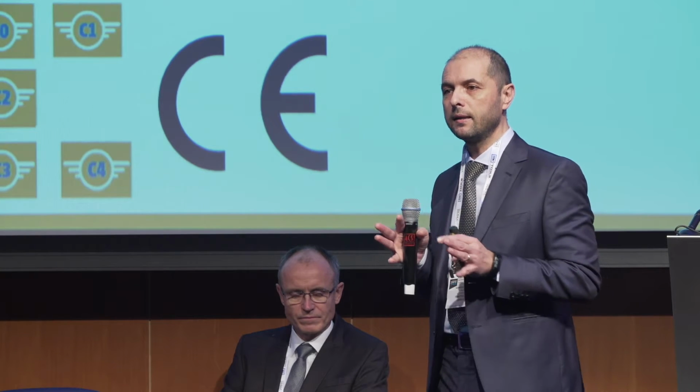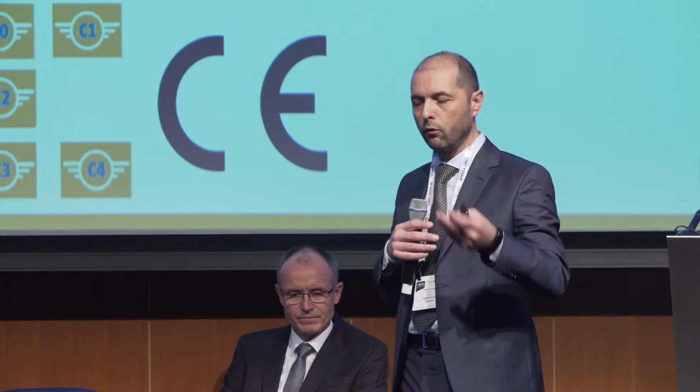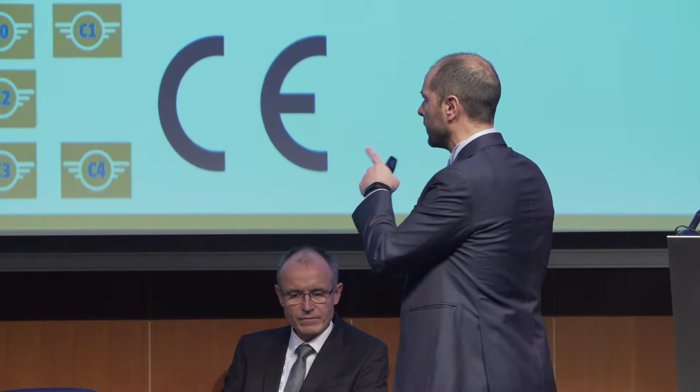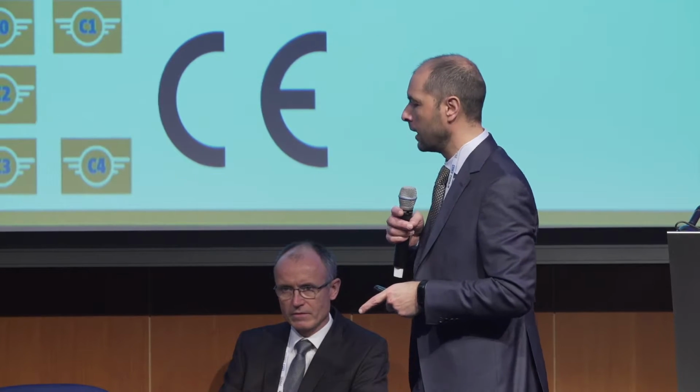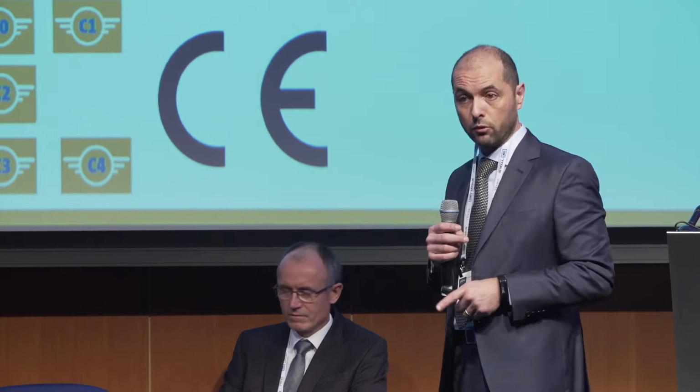And according to them, there will be also a leaflet that will tell you the most important information, where you can fly, where you cannot fly. And then the training that we will see later will give you some additional information. But in general, for example, if you are using a drone C0 or C1, C0 is up to 250 grams, C1 up to 900 grams, you can fly over people. So in urban environment, avoiding to fly over crowds, so you cannot fly over a stadium, but you have very little limitation for this category. And also if you have a privately built drone, so without a C marking, that you build by yourself, and is below 250 grams, still you can fly over people.